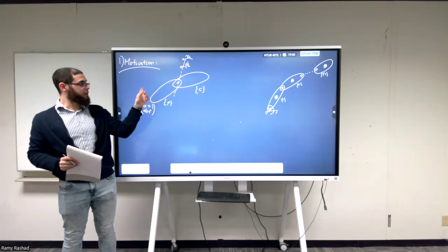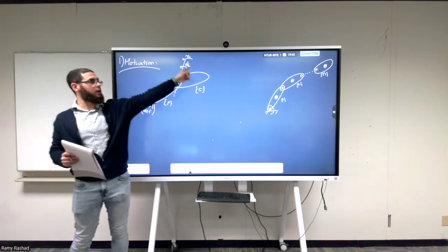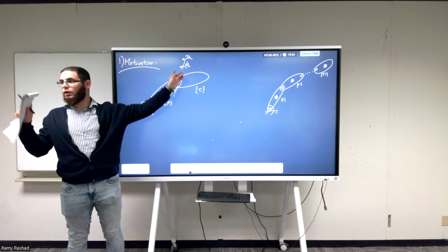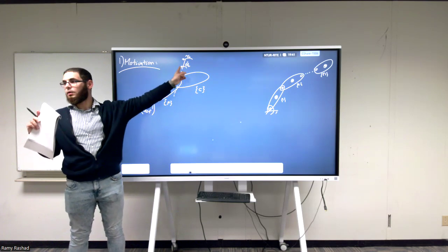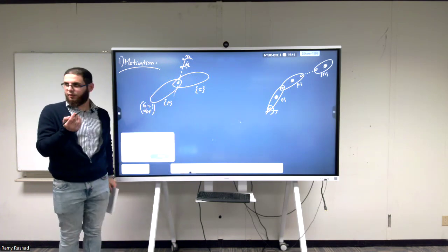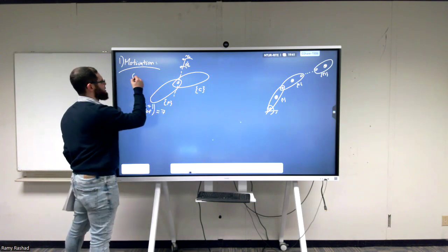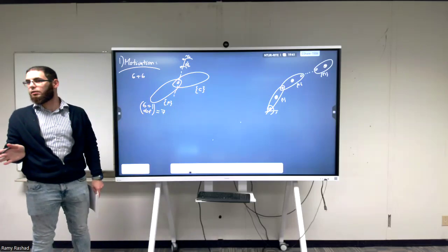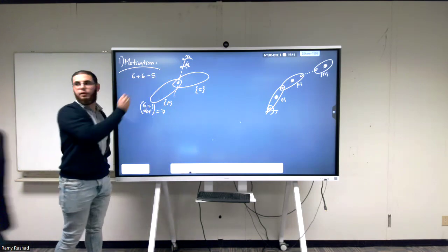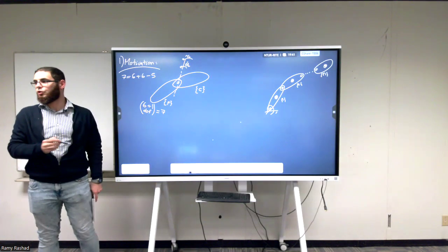Because this one by itself, first of all, is not connected to anything. So this by itself has 6. When you connect it to another body, and it has a relative motion between them, then you can only apply 1 extra degree of freedom, which is this angle. And that's it. So it's only 6 plus 1. You can think of it this way: the 6 plus 1 is equal to 7, right? Originally, it was 6 plus 6 because we have 2 rigid bodies that are not connected. And then you had 1 joint, and the joint constrained how many degrees of freedom? Constrained 5 of the degrees of freedom. Then you were left with 7 degrees of freedom, which is 6 plus 1.